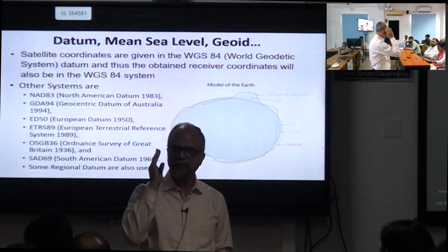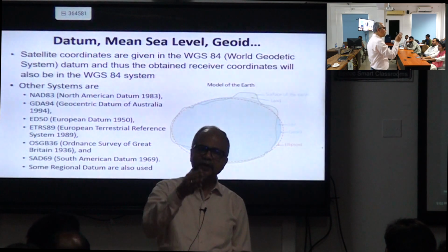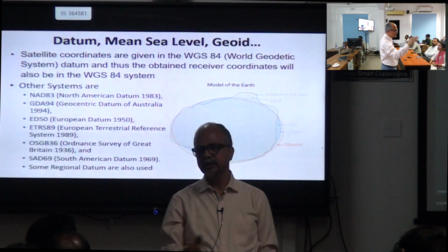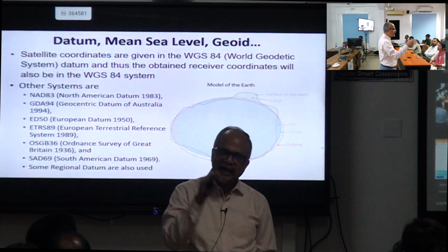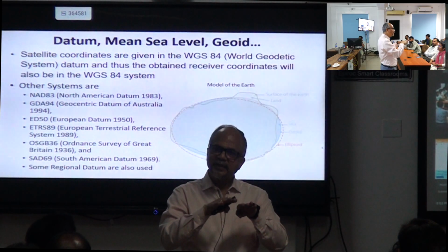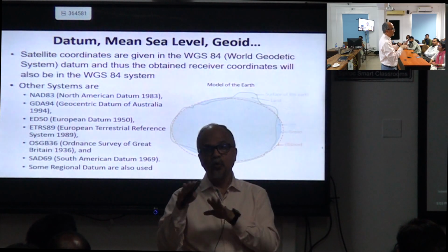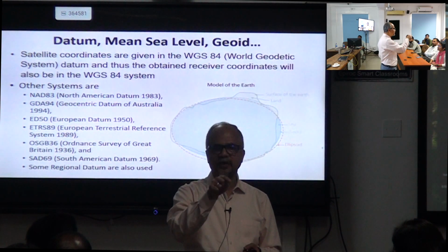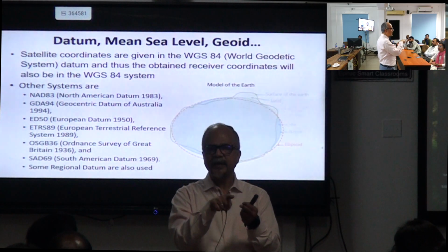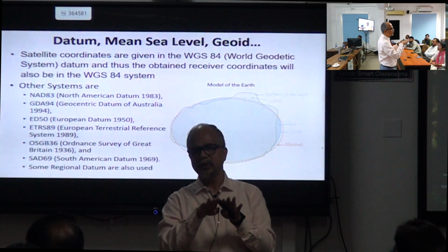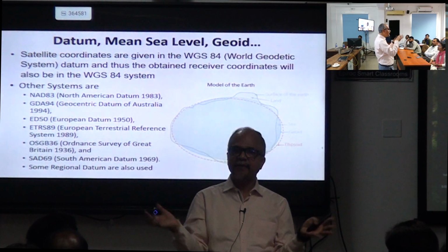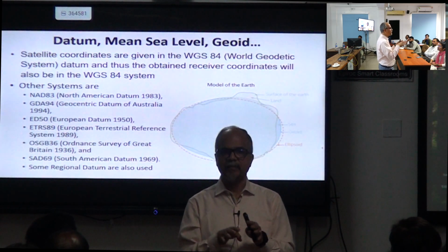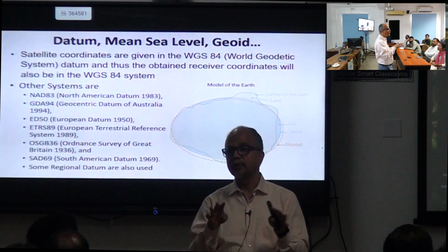This is a very important point. That's why I am bringing this up, because whatever you are getting by GPS will be with a different datum, and in some locations there can be quite a significant difference between these. Google Earth, again, uses a different datum. So the Google Earth elevation, whatever you will get, and Survey of India may not be matching. That will not be matching. Now, different DEMs are also developed by different organizations. So those data may not always match. So your elevation may not be matching.